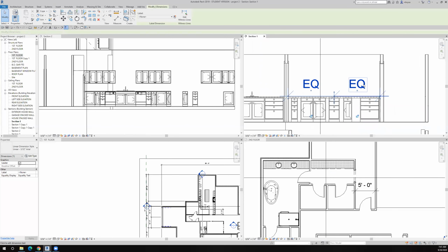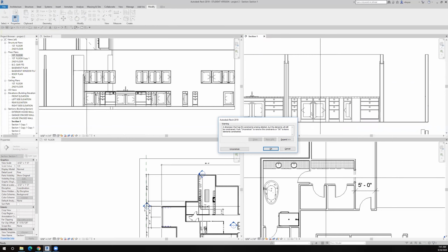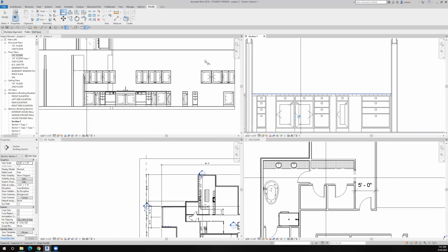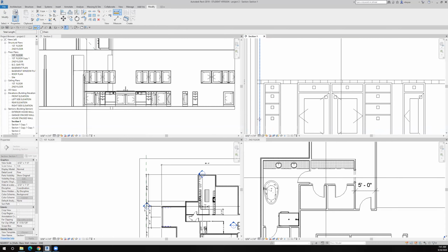All right, and I just delete the dimensions and constrain it. And then I use the align command, which we use a lot. I'm in multiple alignment, so I have to uncheck that. So I'll pick a new object and align that. Then this guy will just measure how much space we have here, and I'll make that drawer the closest to a standard size.